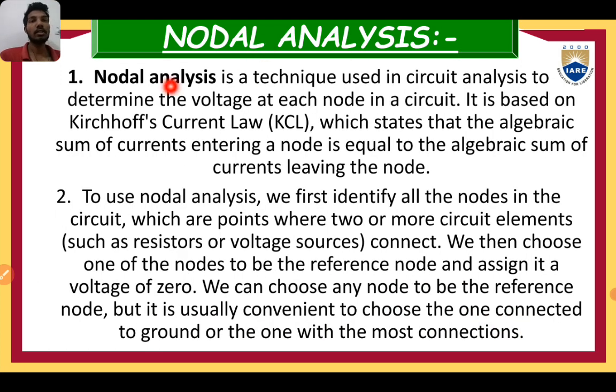Nodal analysis. Nodal analysis is a technique used in circuit analysis to determine the voltage at each node in a circuit. It is based on Kirchhoff's current law, which states that the algebraic sum of currents entering a node is equal to the algebraic sum of currents leaving the node. To use nodal analysis, first identify all the nodes in the circuit, which are the points where two or more circuit elements such as resistors or voltage sources connect.